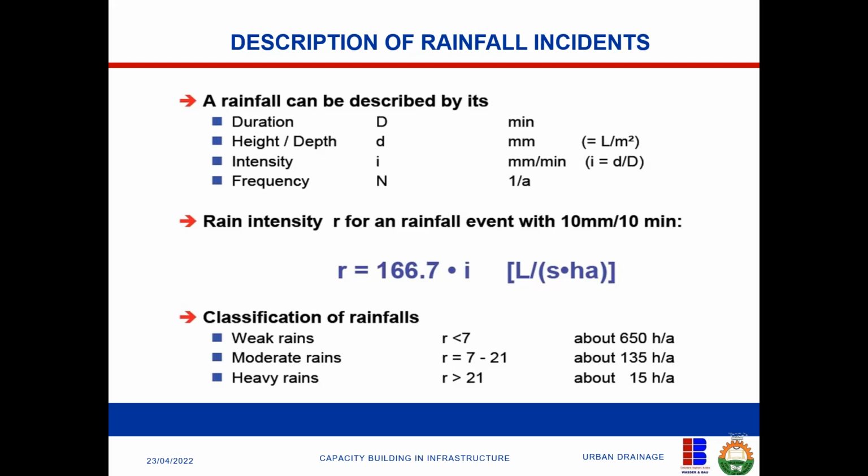So the higher the frequency, the lower the number of years. The higher the number of years, the lower the frequency. The two of them can be used interchangeably. That 0.1 means that for this rain to occur, it is like a 10% chance. But at the same time, that is the rain that I need to do my design, so that my design will be optimized.